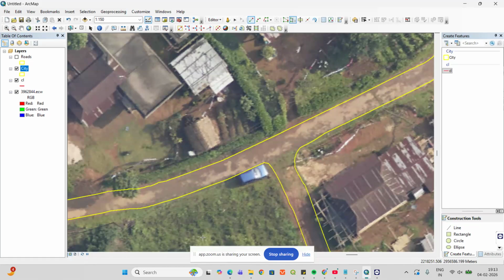Yes, 50 flying teams. A team has 2 persons, one drone, and 5 to 7 sets of batteries. They go by morning 8 or 9 and fly for 3 to 4 hours. They come back, go again after lunch, and fly for 3 to 4 hours. In the same way, they were in the field for 3 to 4 months. They come back, and we process the entire data with the balance 6 months and do mapping work. Then next year we go again to complete the balance 50%, because you can't continuously fly there, as they have long monsoons also.